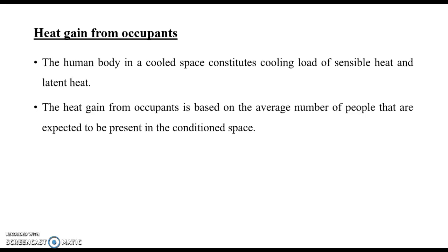So we are going to account for the amount of heat released from each occupant. The human body in a cooled space constitutes a cooling load of sensible heat and latent heat, and the heat gained from occupants is based on the average number of people expected to be present in the conditioned space.